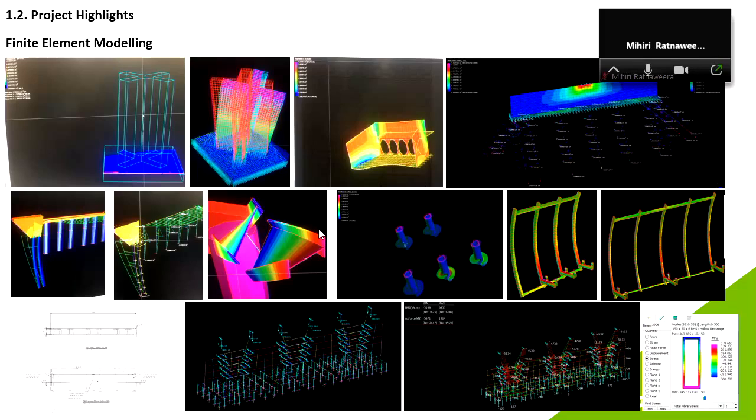In addition to the conventional structural model, I did some soil and structure interaction analysis. This is where we get support from the geotechnical engineers and we get the bidirectional soil stiffness springs. Those get attached to the structural elements, and then you can analyze the deflection, the settlement, construction sequencing, and also secondary issues like force and displacement effects.